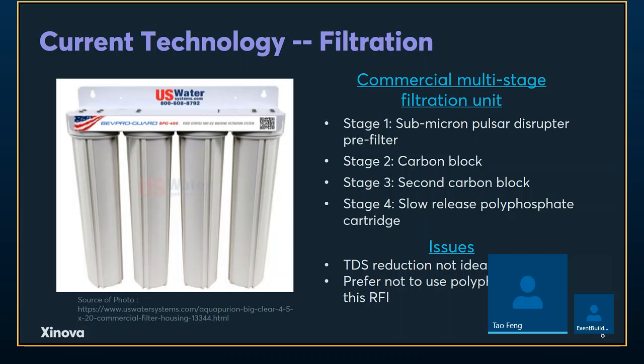Shivani, can we turn to the next slide? Thank you. So first, the filtration. Filtration is a very common water purification method. Most basic filters are simple porous materials that exclude large particles and bacteria. More complex filters can include additional materials, for example, silver nanoparticles, which can kill bacteria or mold trapped in the system.